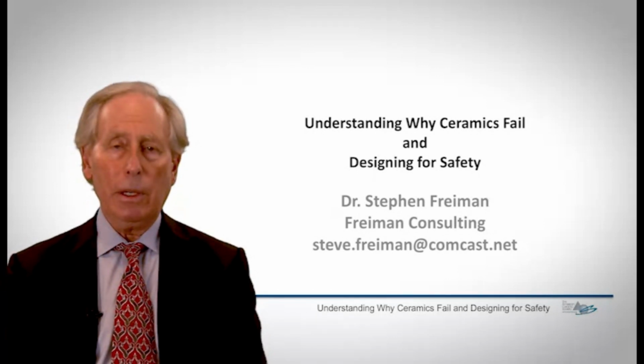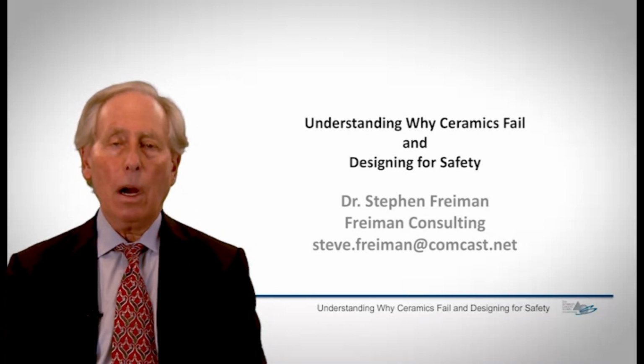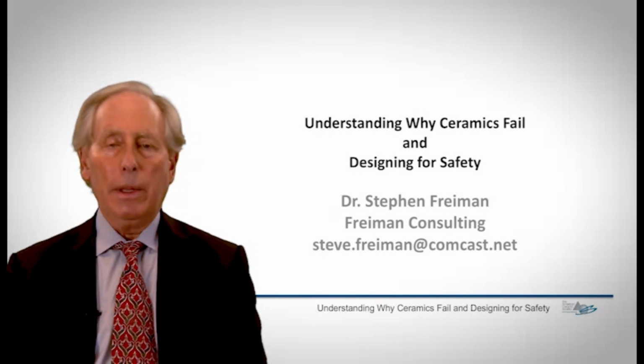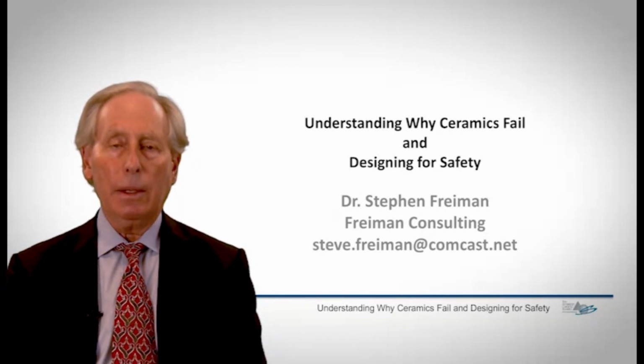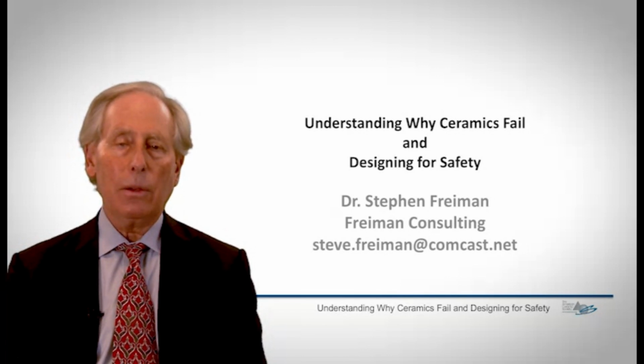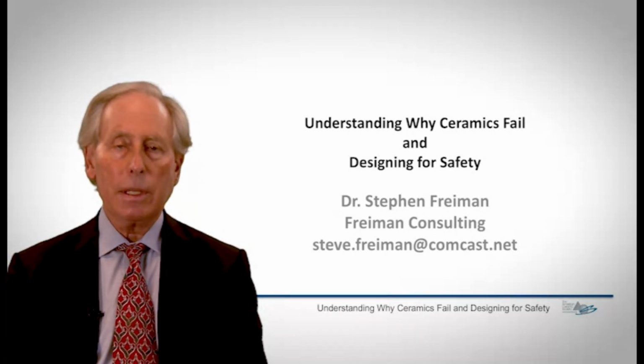Ceramics are wonderful materials. Those of you who work in our industry recognize this because of their high temperature properties, their hardness, their electrical properties, their optical properties at times, their transparency. We use them in many different applications. But they have one serious drawback. They are brittle, which means that they can fail suddenly under stresses that we don't recognize are present or which are there for other reasons.